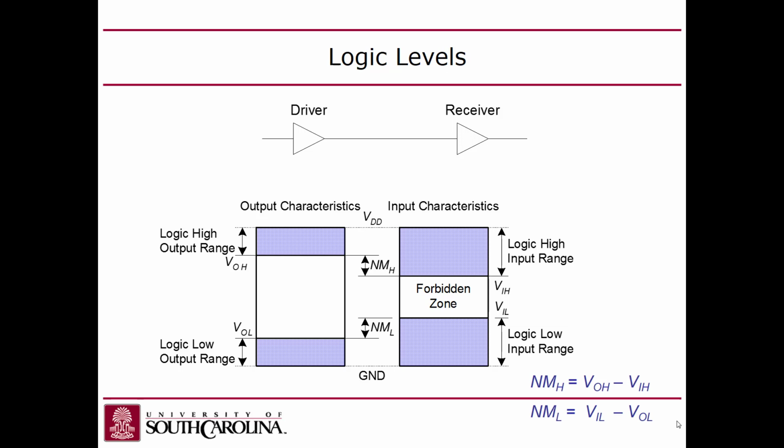Not a repeatable error, but a random error. They call them transient errors or soft errors. Errors that just kind of randomly appear as a result of noise on the power supply or crosstalk. So a gate can have a transient error because of activity of circuits nearby on the chip, or radiation can cause this too.